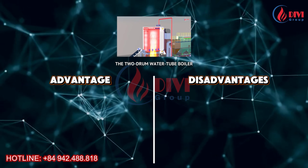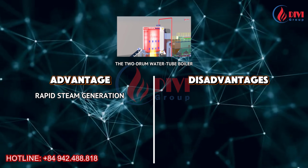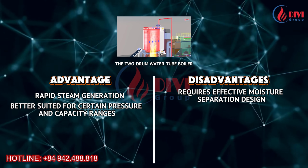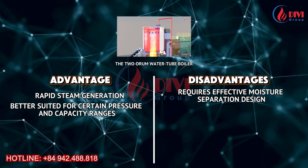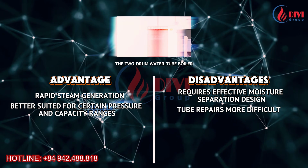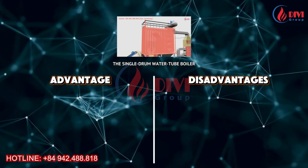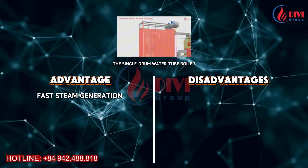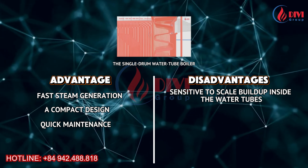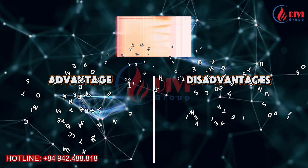The two-drum water tube boiler generates steam more quickly and is better suited for certain pressure and capacity ranges. However, achieving high steam dryness depends on effective moisture separation, and tube repairs are generally more difficult. The single-drum water tube boiler offers fast steam generation, a compact design, and quick maintenance when properly designed, but it is also more sensitive to scale buildup inside the water tubes.